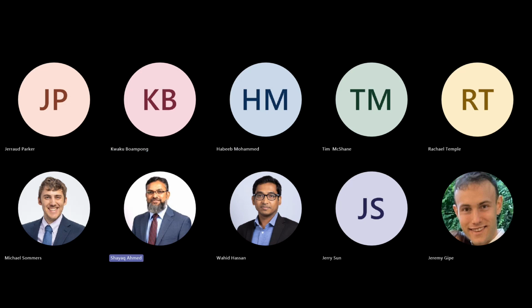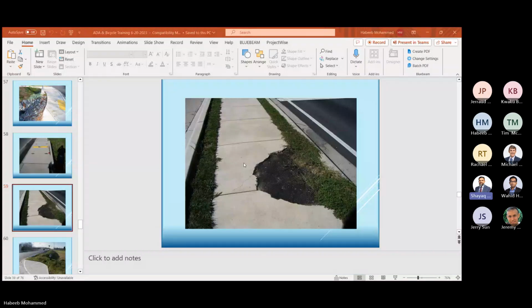So as you said, even if the running slope of the roadway is steeper at ramp locations, there is no exception. All the ramps have to be ADA compliant. But you should be able to tie in if you follow the roadway grade for the rest of the sidewalk. Only for the sidewalk can you match the running slope, but the ramps have to follow that criteria. If it is parallel, they need to follow that criteria. If it is perpendicular, all those slopes and widths have to be met.